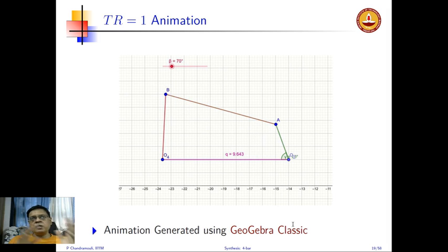There were certain positions for O2 which were not allowed because of violation of the Grashof condition. And then I also showed you how to do this for negative alpha as well as TR equal to 1. TR equal to 1 is a simple case because essentially the choice is to be on the B1 B1 prime line, outside of course, points in between B1 and B1 prime.